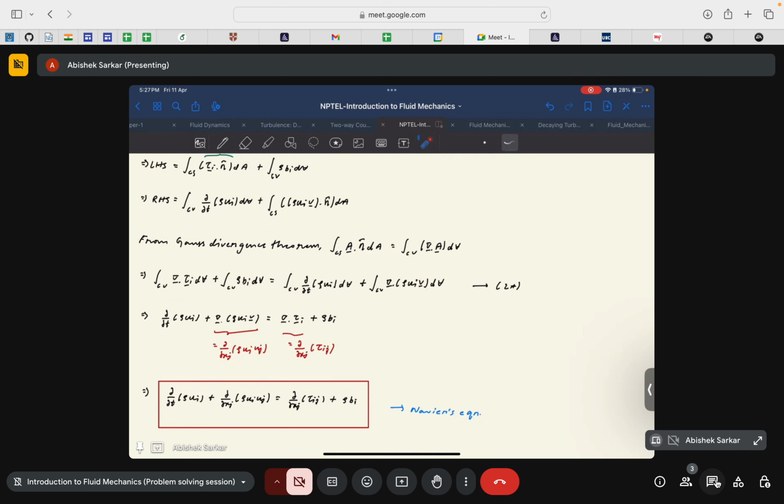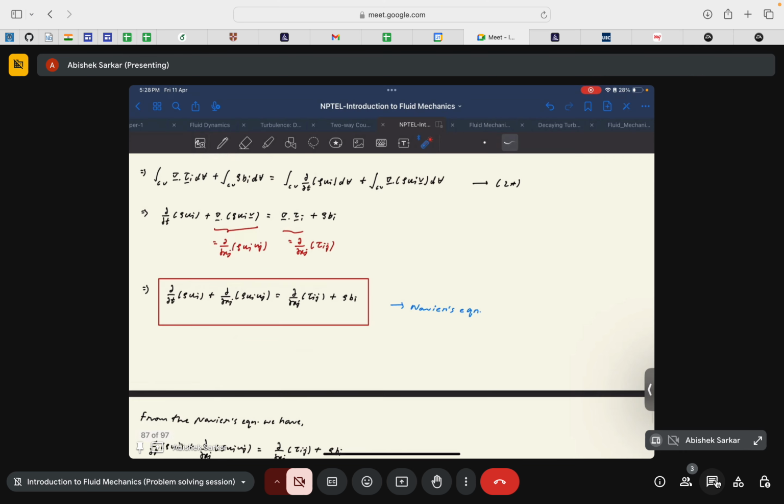Okay, and why is this equation very important? Let me tell you. The Navier-Stokes equation is just the understanding that the shear stress, this term, varies linearly with the shear strain rate of the flow field. So basically, if we substitute the fluid as a Newtonian fluid in this equation, we will get the Navier-Stokes equation, which is of course the cornerstone of fluid mechanics.